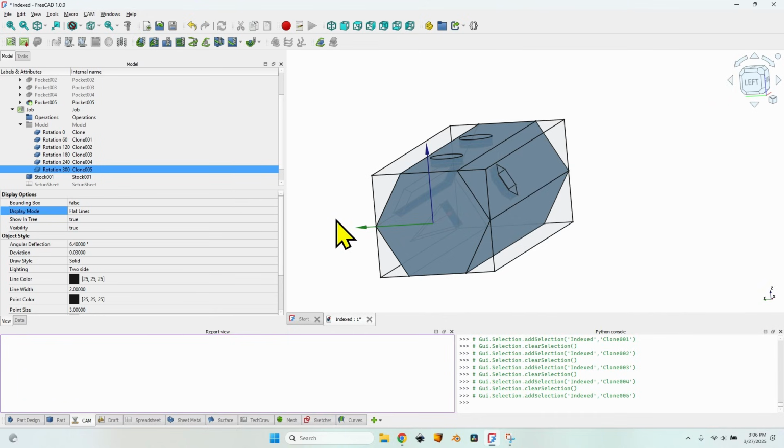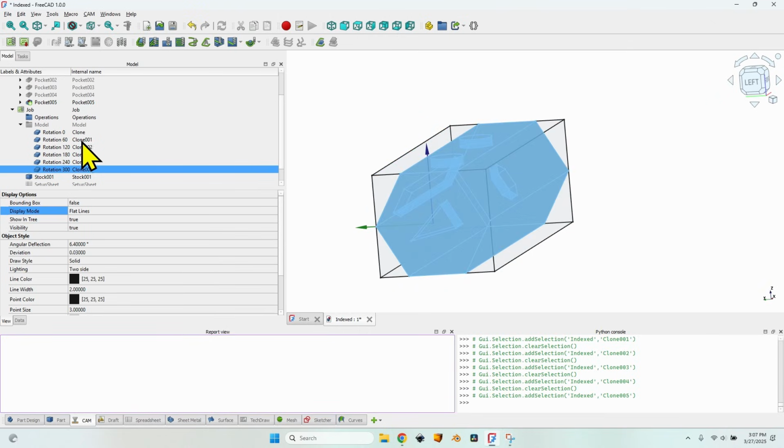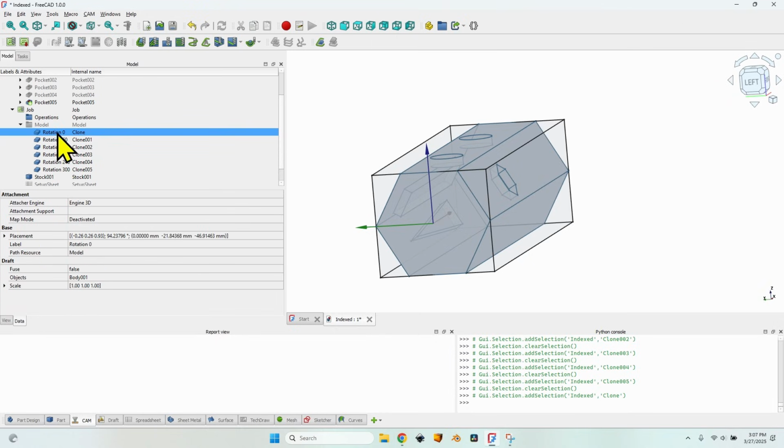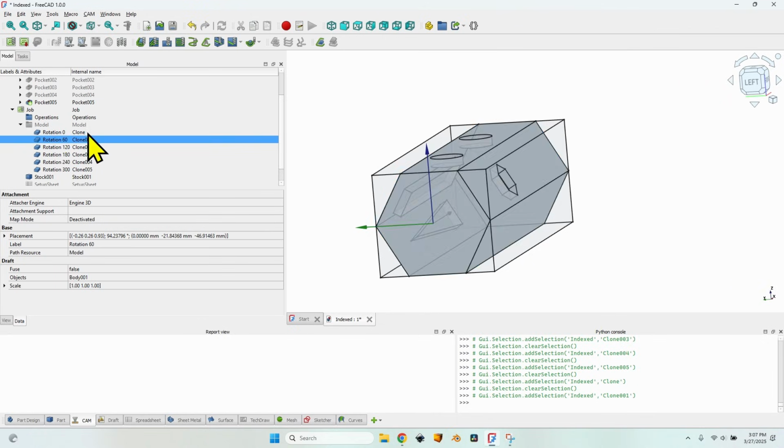Of course it's a simple hexagon. If you don't know exactly the angle of a face, it's just as simple as I've shown you in the beginning of the video. When rotating all the objects to have one of the face perfectly flat, just measure the angle and use that angle to have the rotation. But the objects are not actually rotated. So I will go to the data tab, select each of them one by one, of course not the first since it is a 0 degrees rotation.